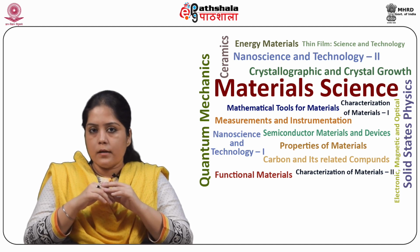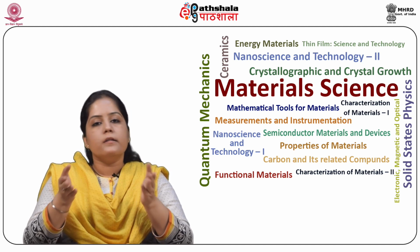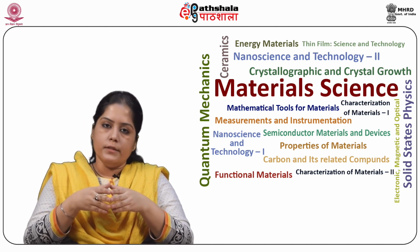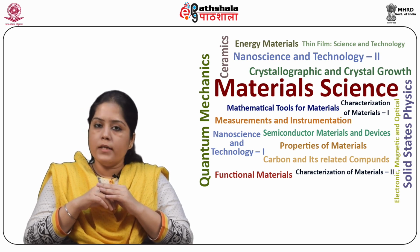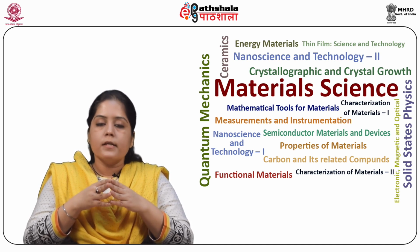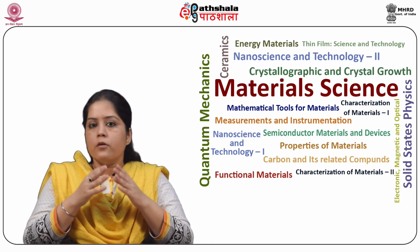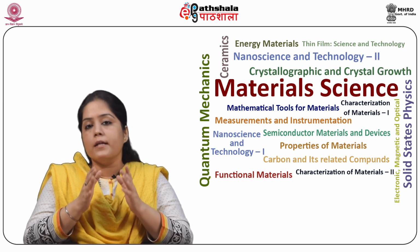3000 series are alloyed with manganese and they can be work hardened. 4000 series are alloyed with silicon. They are also known as silumin. 5000 series are alloyed with magnesium.